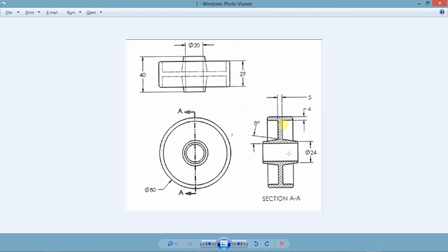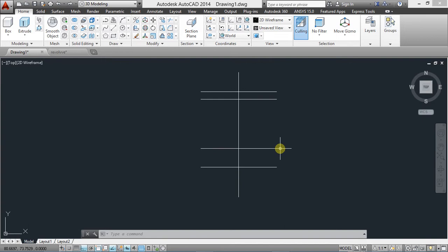So we are concentrating on half of it, that is 1/4, a quadrant of it. You are sketching the quadrant, that is the 1/4 of the entire object. We will sketch one part, then mirror it to have a half. Then with that half, it will enable us to revolve it. We're interested in designing part of it, just one of the total 4 parts, a quadrant of it.